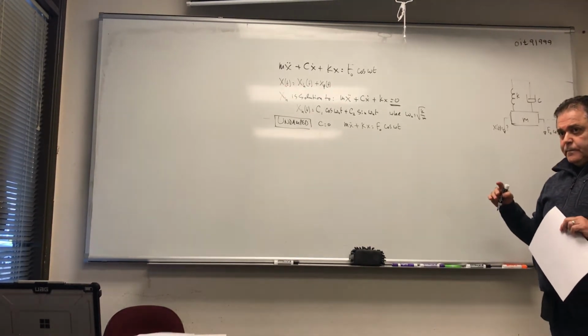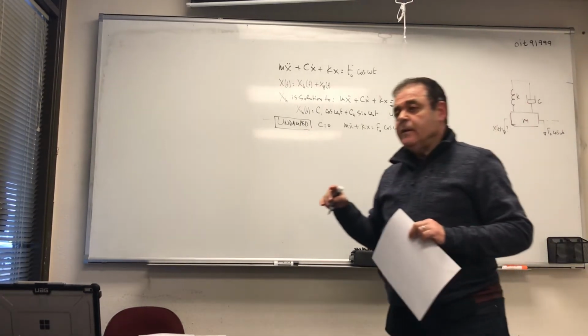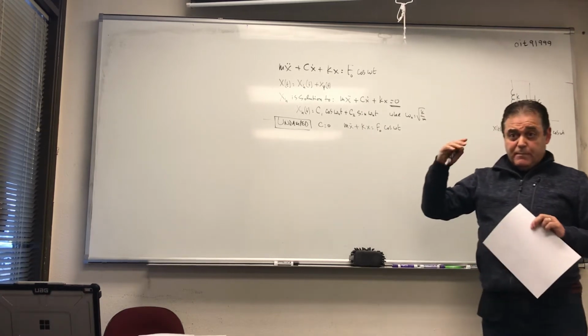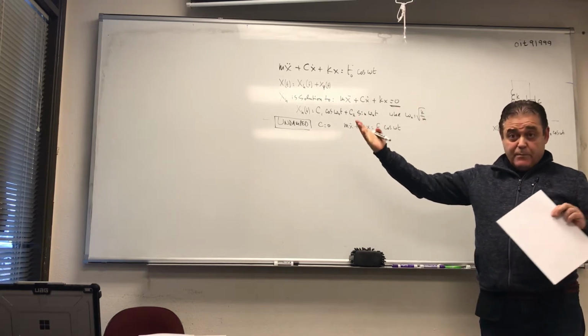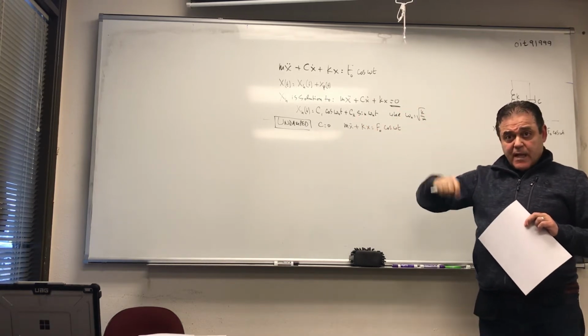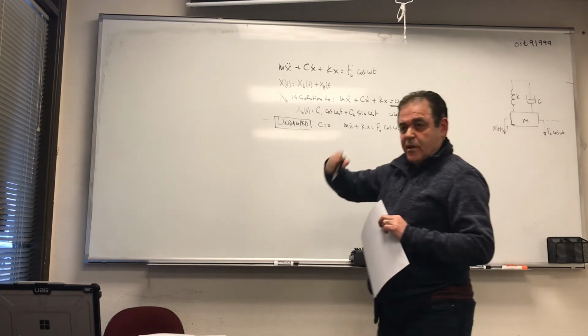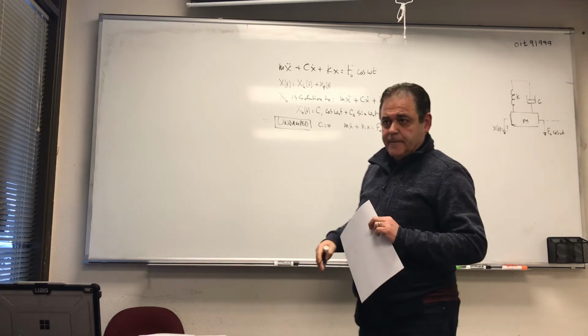For undamped, is there always a forced vibration? Because omega n is the natural frequency, right? Yes, omega n is the natural frequency, meaning it's the free vibration. That's the type of vibration that, whether you have damping or not, is a characteristic of the system. So if you let it go, that's how it's going to vibrate.